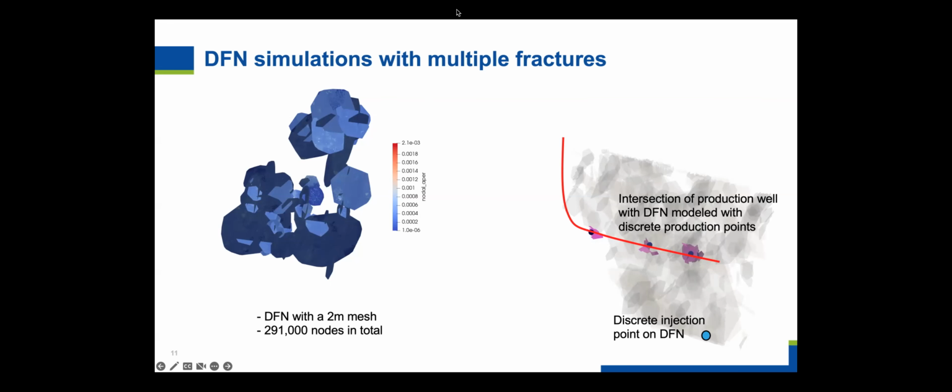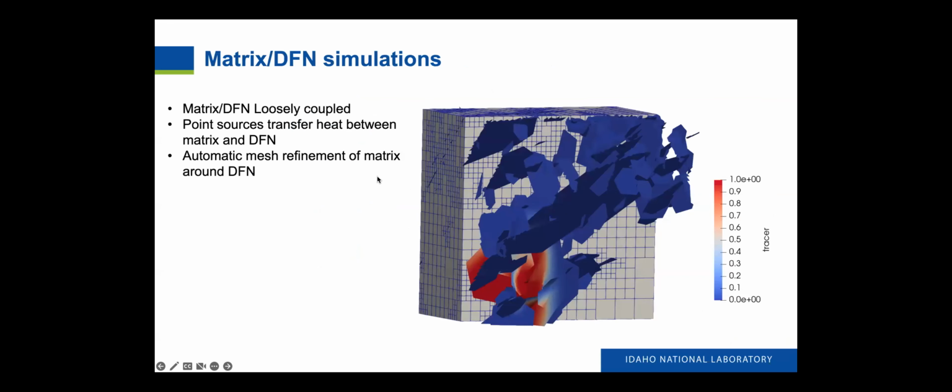If there's no further questions, I just see a question come in. McCool, go ahead and just ask your question. Okay, I was just going to ask, and maybe I missed this, I'm sorry if I did: is the fracture modeled as a discrete crack with a finite width, or is it part of the matrix grid blocks with a higher permeability and porosity? Oh, well, it's modeled as a 2D plane in 3D space, basically. Yes, but is that plane part of the matrix in terms of how you grid it? Is it just a high permeability, high porosity grid block?